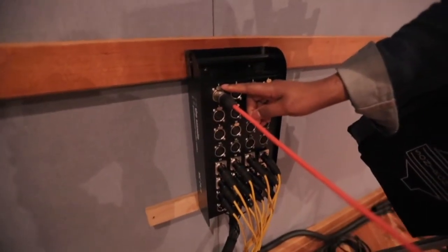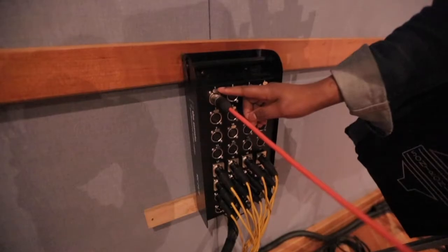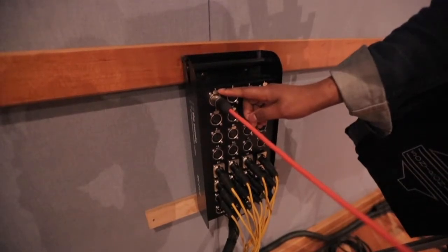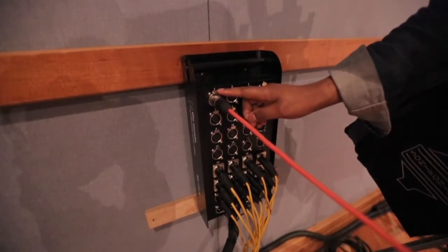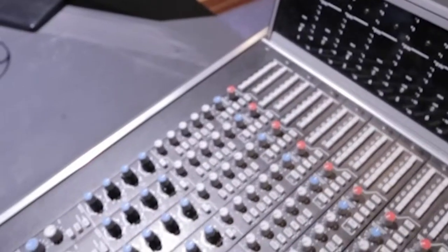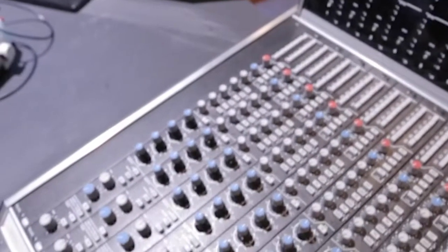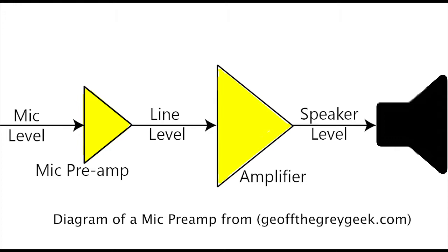With a routing matrix on a desk, you can choose any number of channels, and these will depend on your decision. When the signal enters the desk, it's amplified by the channel's preamp from lower mic level to line level. This is done by adjusting the gain pot.